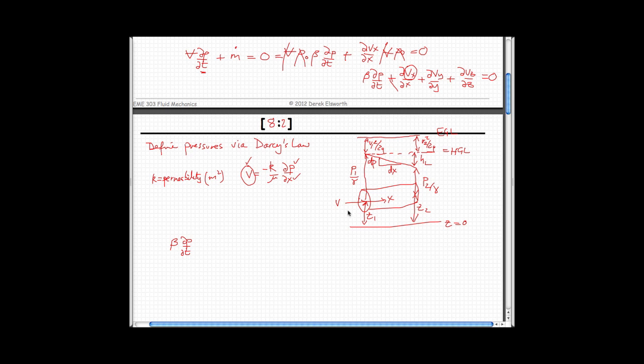It's a minus sign. Why is it a minus sign? Well, it's a minus sign because if you look at this being the x-axis, and this being the pressure axis, then this pressure change is a negative pressure change, but it gives a velocity V2 in the positive x direction. So it gives a positive velocity. Velocity is a vector quantity, and so the negative sign is just the fact that fluid flows from high potential to low potential. There's nothing more than that.